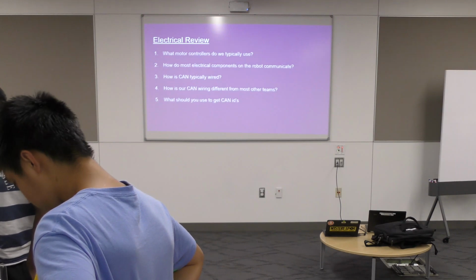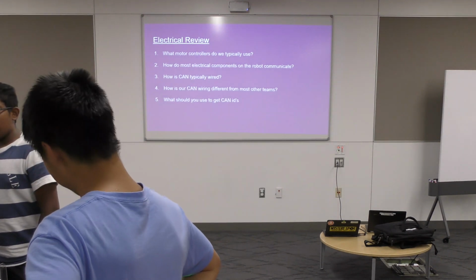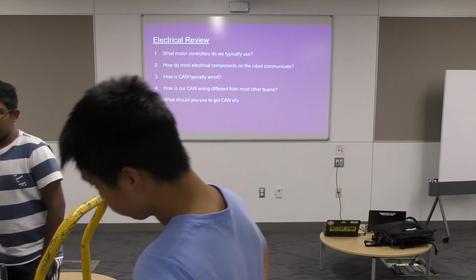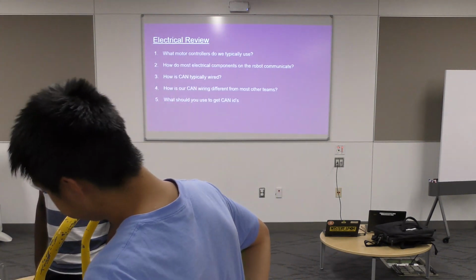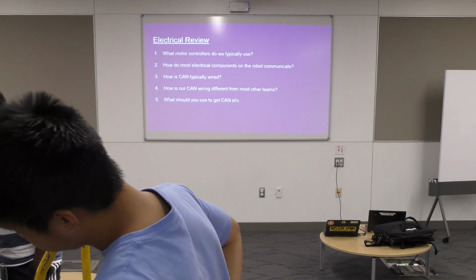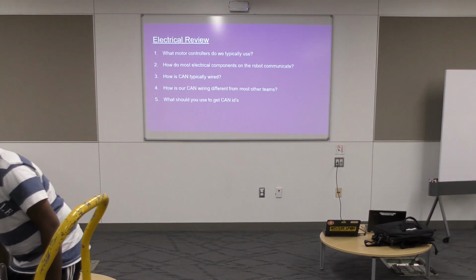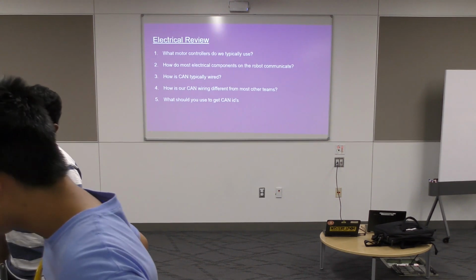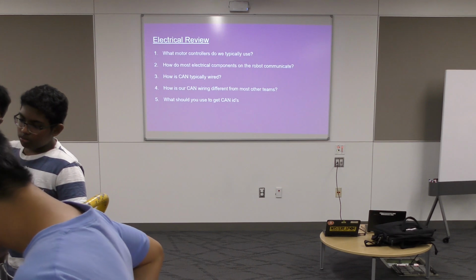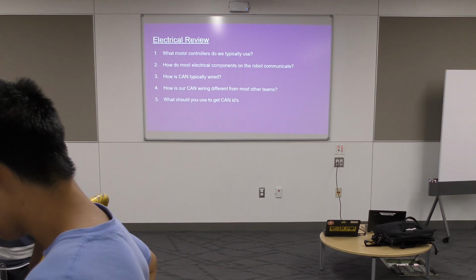Let's see what else is important. How many of you have heard of pneumatics? Pneumatics essentially use compressed air to move pistons in and out. The way to control pneumatics is this little module here. It's called the pneumatics control module. The pistons are simple. They're either fully extended or fully closed.